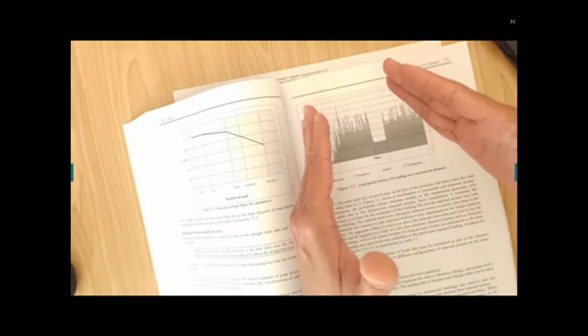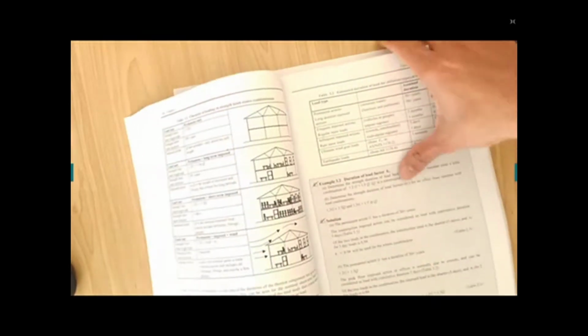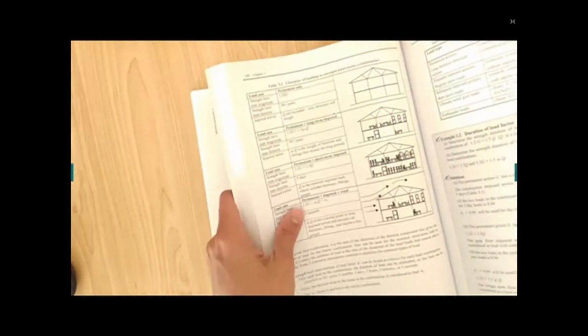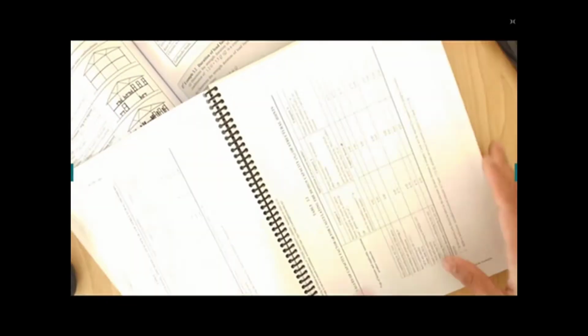Ultimate point meaning that you have 50 guests come to your house. You might have this one. In the normal situation, you have 2-3 people. That is not what we are designing. We are designing for the ultimate situation. In that case, you may not have these ultimate situations coming all the time. So the standards will recognize that. These are the tables that we're going to use, that you have only dead load 1.35 G. By the way, I need to show you what I'm talking about.